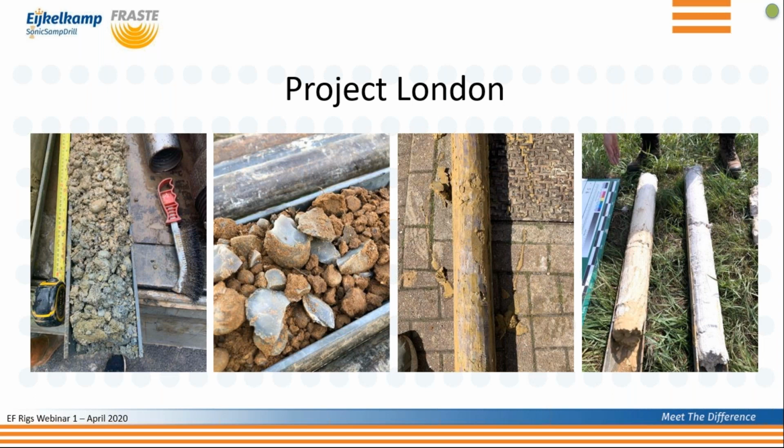If we look at the different types of clays in London, how do you cope with that with a sonic? London clay's no problem. The same as a cable percussive rig finds it no problem. Yeah, so when you get into the Lambeth group, where it's very, very dense clay with sand lenses, cable percussive can drill it, but it struggles and it becomes quite slow and laborious. Whereas the sonic cuts through it, drills through it, no problem. And obviously you're cased at the same time, so it's not an issue.